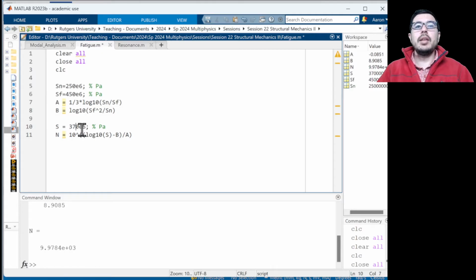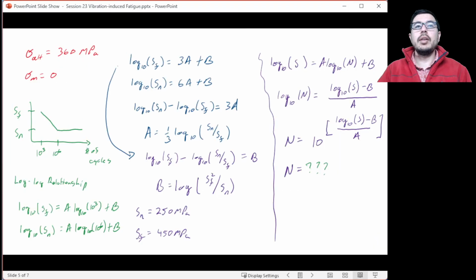So typically, we want to make sure that we are not designing for low cycle fatigue, that you're designing so that you're underneath the endurance limit. Because if you design here, you don't know exactly how many cycles you're going to have. Now, if you keep things very controlled and you want to have planned obsolescence, you can do quite well in terms of having replacement parts. But typically, we want to avoid designing for this range. So we got values ranging from 10,000 to 14,000 to 38,000 using our simulation and our analysis.